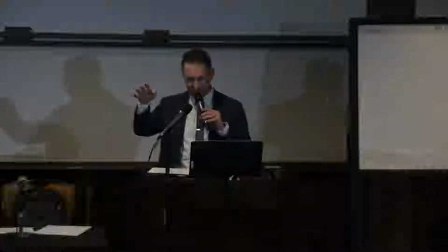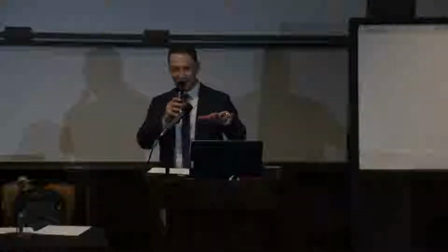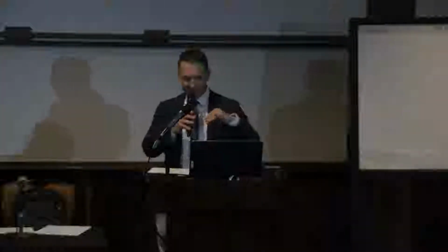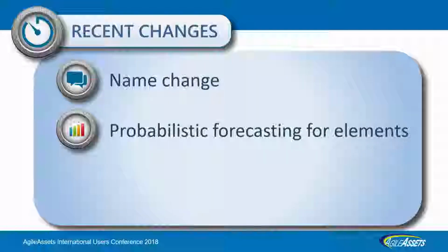In other words, they're basically defined by an equation, and that equation typically doesn't allow for random variables, but that's still in there, and that works great. And I'm going to show you another piece of that in a little while that really works nicely. Gives you some comparison things to do, but we've added deterioration curves for every single bridge element in order to forecast the condition of each of those elements over time.